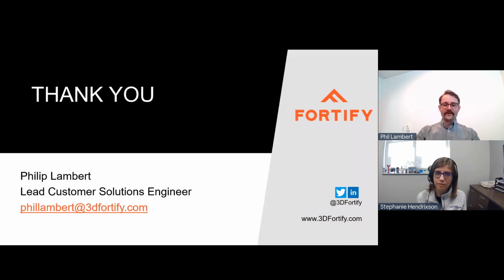But understanding what your part looks like as it comes out of the printer, and then the result you get after sintering, is something that they've had to think very critically about when leveraging Flux Developer to optimize their printing, right? When you're not dealing with sintering, your end part is the part that comes off the printer. When you introduce the sintering step, how you cure the part, what the surface finish looks like, what those support structures look like, what your resolution is, and what tolerance you have are all a function of how that part changes when it goes into the sintering furnace. And so yes, it has to be included in your DOE for your Flux Developer workflows. And if you have more questions about that, happy to have a conversation if someone has a goal for developing some ceramic materials.